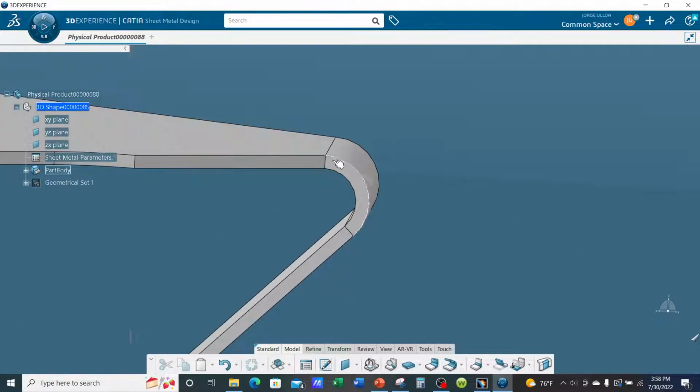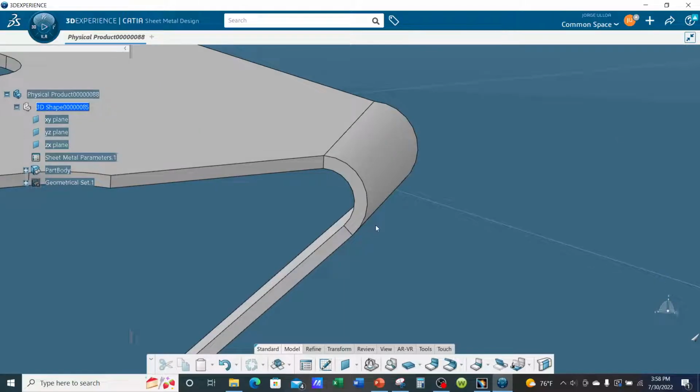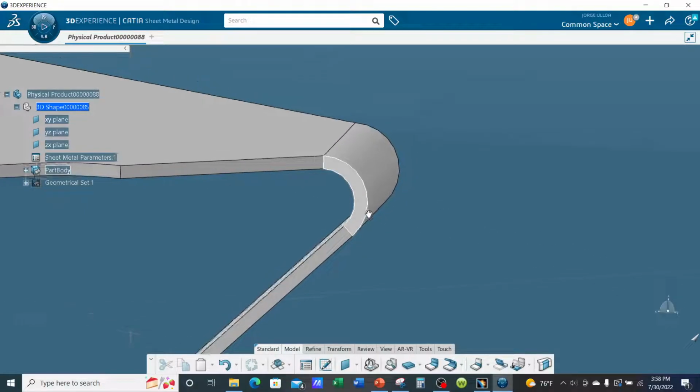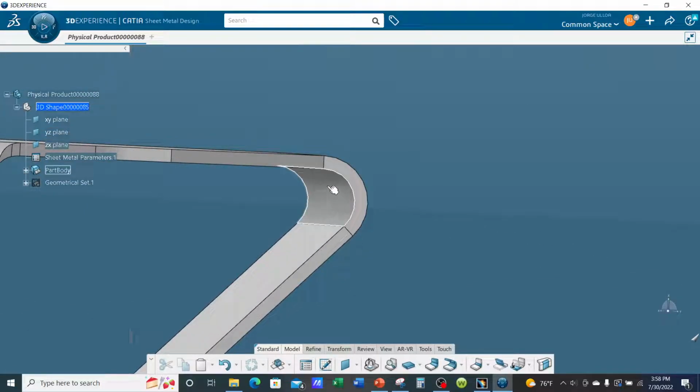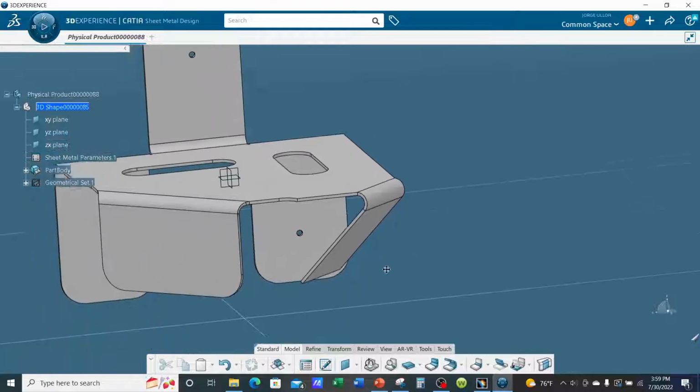If you're using a brake press or maybe you're using a tool to hydroform it to give it this bend radius, the fibers on the outside are feeling a lot of tension. The ones here on the inside bend are feeling compression. Okay, so let's talk about K factor.